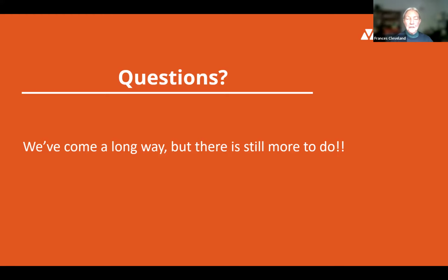We may move to something where 61850 and DNP3 is more tightly coupled if we see a particular need for it. At the moment, we're just trying to establish that the semantics are the same and that people will then implement mapping tools if they need it, or simply awareness of the functional requirements, and here are the communication requirements, whether 61850 or DNP3 using 1815.2.